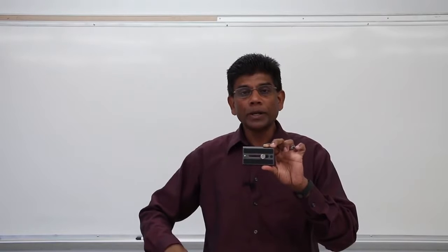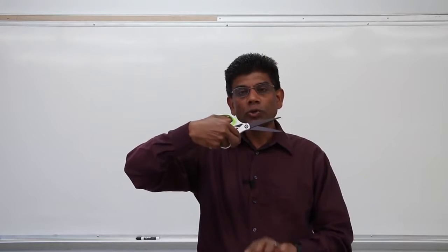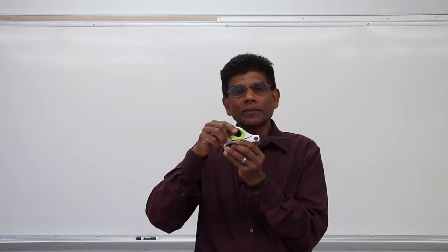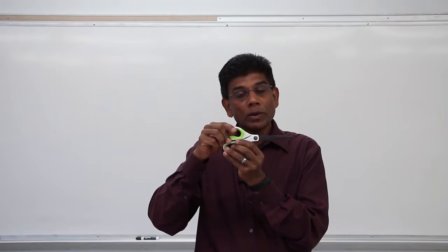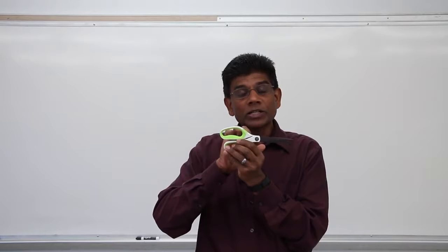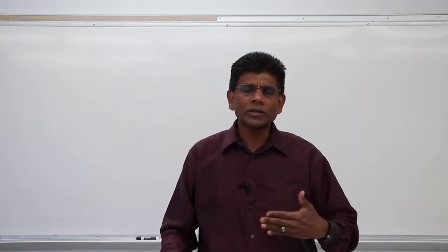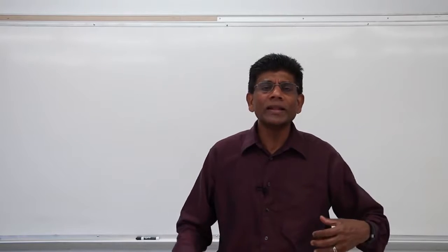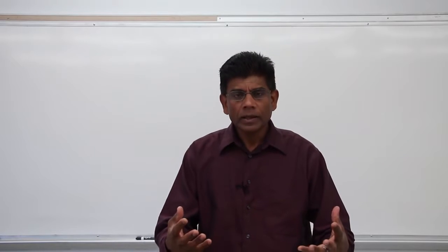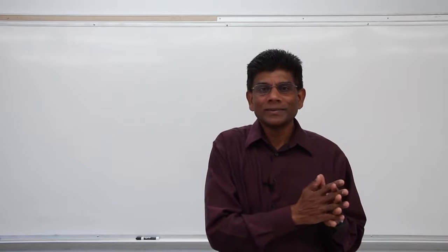On the other hand, a pin support such as this allows only rotation. It doesn't allow any horizontal movement or a vertical movement, meaning the pin connection will give you two support reactions. Now, when I say reactions, reactions are caused when there is resistance. Reactions are created when the support restricts your movement or the support eliminates a movement.